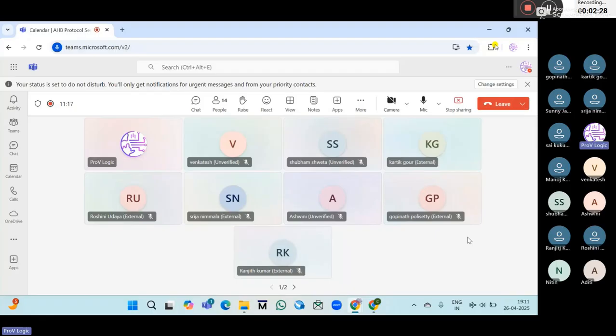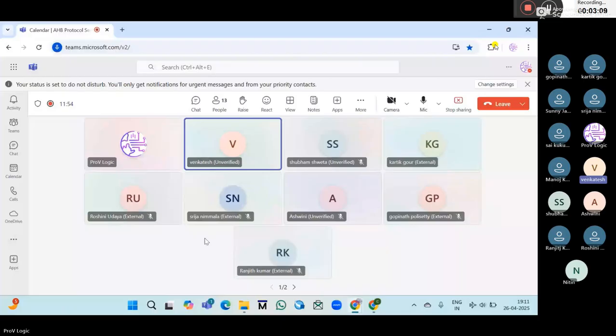Okay. Any other doubts from the APB protocol? Can you tell me what the features of the APB protocol are and what the limitations with APB are? It is used for low power, and no pipeline. Okay, write and read is dependent. It won't have separate channels for write and read.